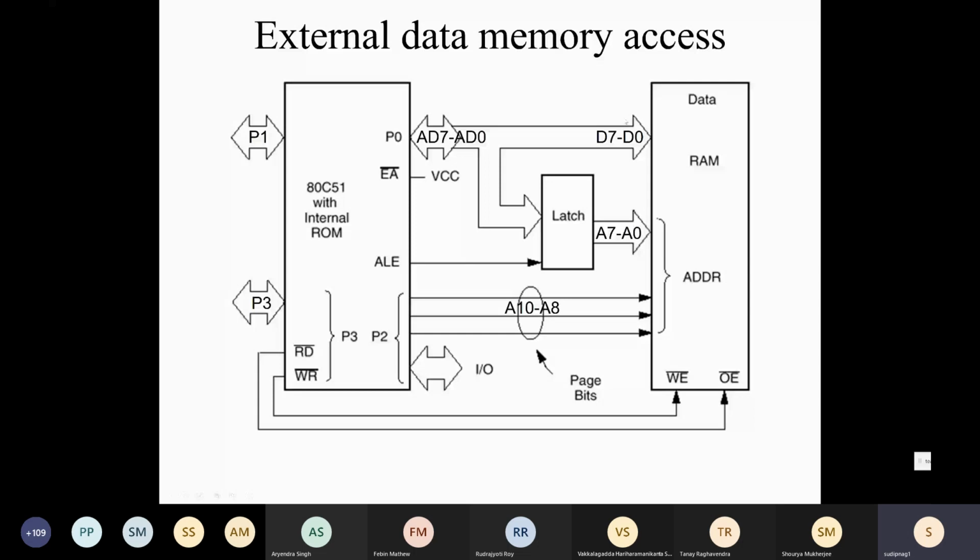Where it will go is determined by the address lines. Based on the exact address value, that will be decoded inside this RAM, and then one single 8-bit location somewhere inside this RAM chip will get selected, and then writing will happen to that one very specific address location where 8 bits are present.